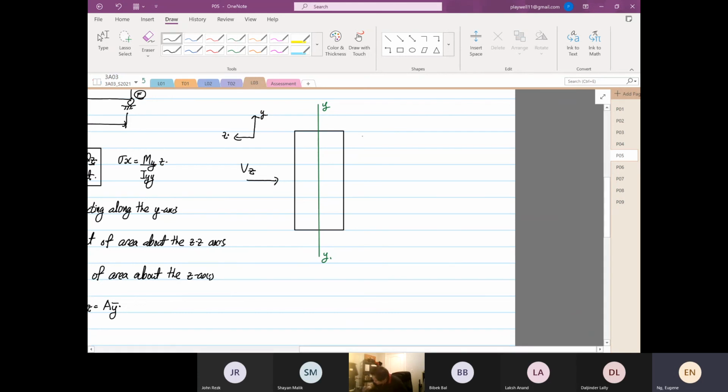So the shear intersecting plane is still the X, right? The intersecting plane, so this area, is still the same area of interest. Now the shear force is in the Z direction, and this is equal to the shear stress in ZX. So now this will be equal to what? So watch this. This is Vz over Iyy, right?